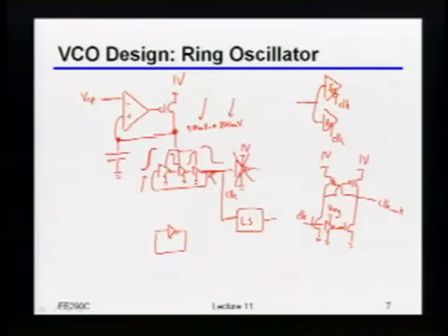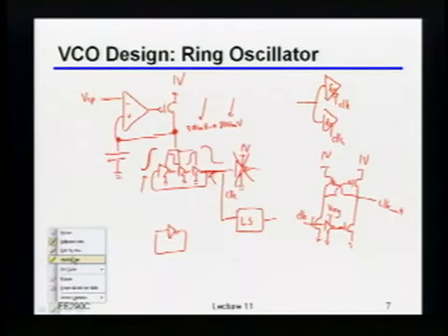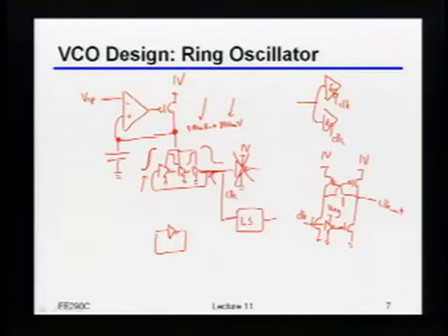A convenient way of doing that is just to have two comparators, one running off the true phase of the clock, and the other one running off the negative phase of the clock. So if I just took this thing and fed that directly into these two comparators, is that going to be good, or am I going to be unhappy? Chintan's unhappy because I guess he had to do this once before. So anybody else? You should be unhappy, by the way, but now we just have to figure out why.